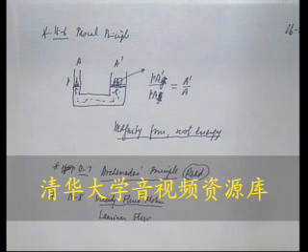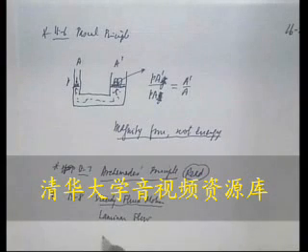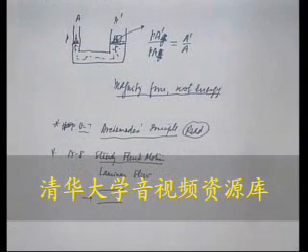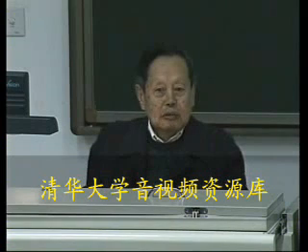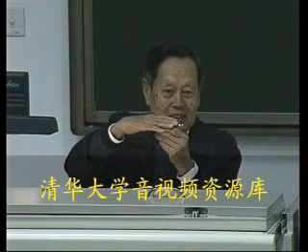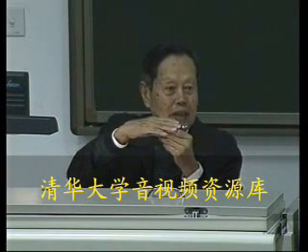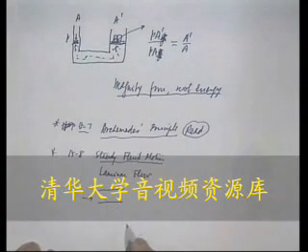Steady flow motion is also called laminar flow. Laminar means layer by layer. So, if you have a tube, like a water pipe, and you apply pressure on the side, then the water would flow inside, but the water near the surface would flow with zero velocity because there's friction. The contact with the tube would slow down the water, but the water in the center would flow rapidly.